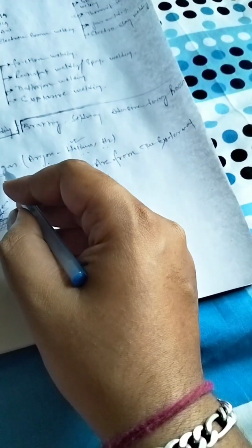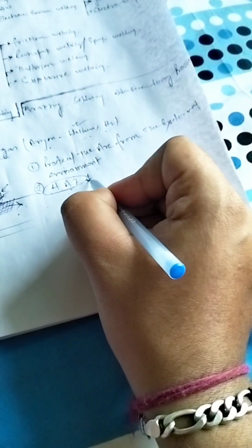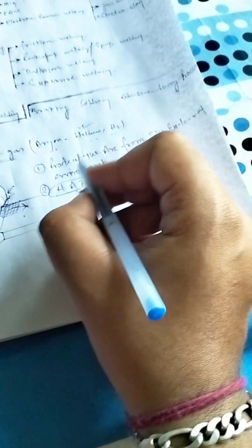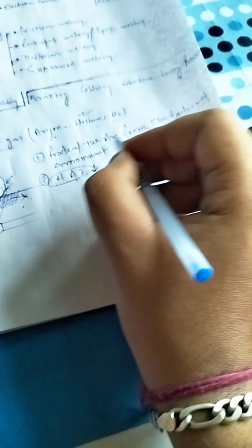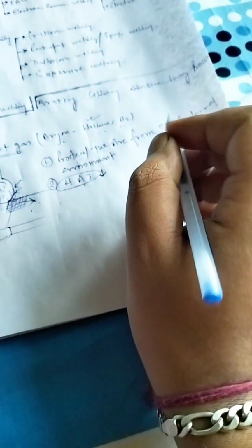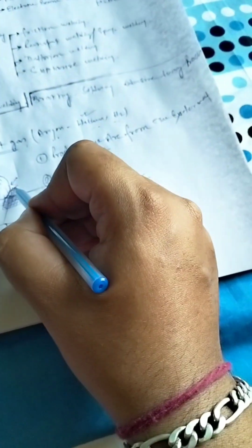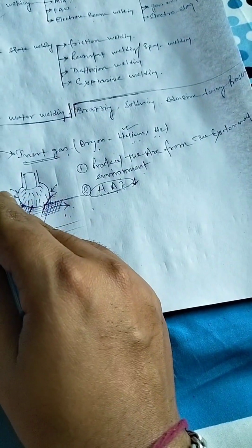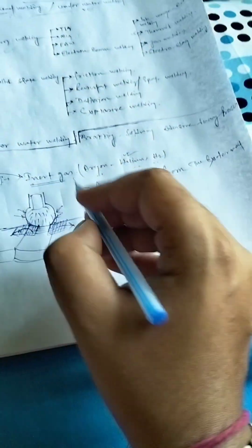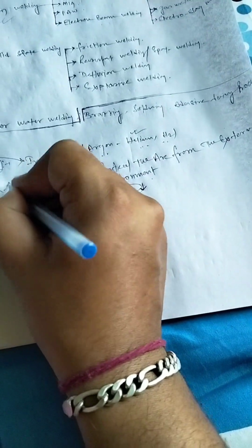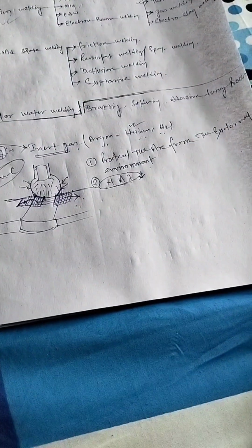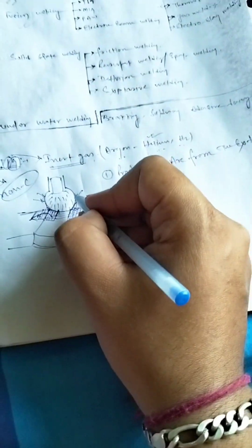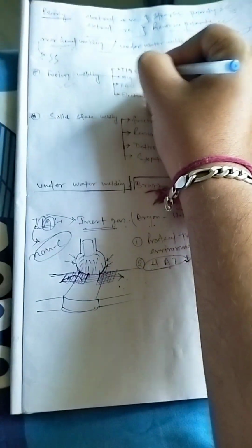The inert gas compresses the arc, so that we get a very small heat affected zone, a high quality weld is performed, and gaseous defects are very few. This is the main function of the inert gas. Here we use the non-consumable tungsten electrode, and for mass production we basically use TIG welding.